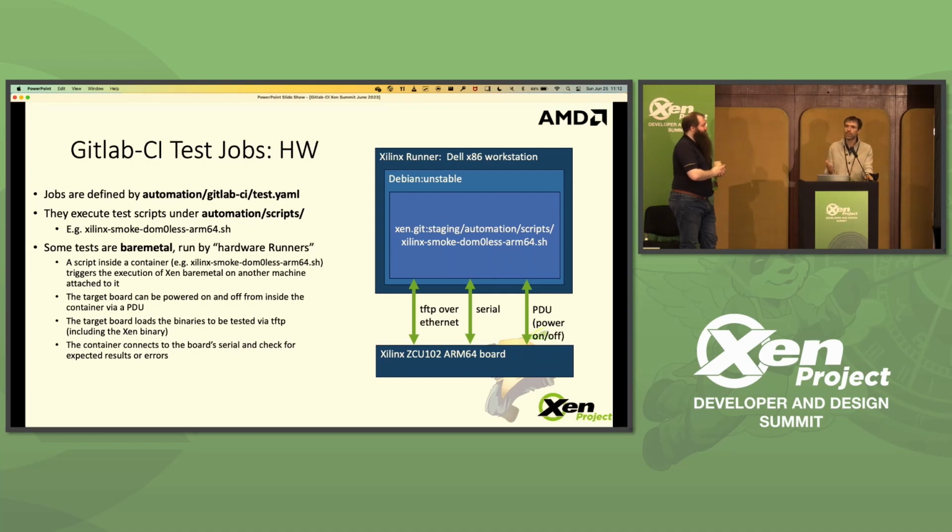So the script is like 90% in common with the QEMU script. However, what it does is trigger a real board reboot. It connects to the real serial of the board, and there is a real TFTP server running, rather than whatever fake TFTP server you use with QEMU.